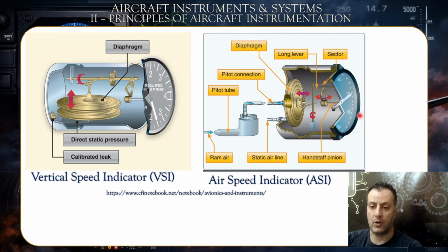Okay? And this is how it works. So it depends vitally on the ram air, the dynamic air being inhaled by the pitot tube. This is why, if in any case the pitot tube gets pinched, or it gets stuck on something, or something gets into it, it will prevent the air from moving freely on the inside, which will cause wrong measurements.